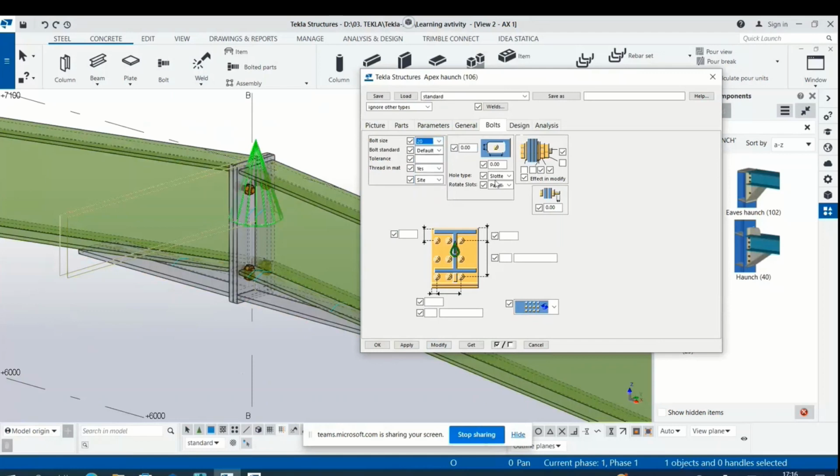The middle connection between beams is usually called an apex connection, and usually it is done with a small haunch, the same as between beam and column, but smaller. Usually, the joints for this kind of frames are semi-rigid connections.